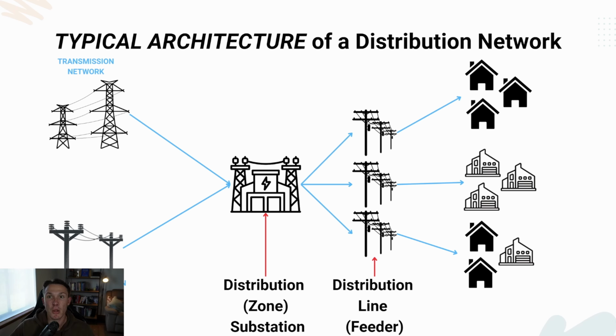And so a lot of these zone substations are connected by that sub-transmission network, with a major substation having a connection to the transmission network. So zone substations are more commonly fed by the sub-transmission network, and it's more of a rarity that they are fed from transmission networks. However, the infrastructure required to support both connections is largely the same, which we'll get into now.